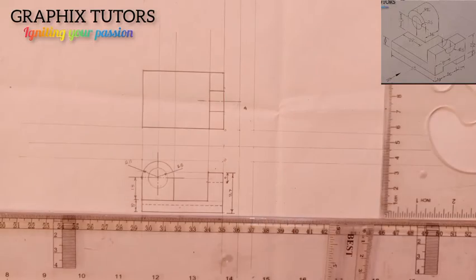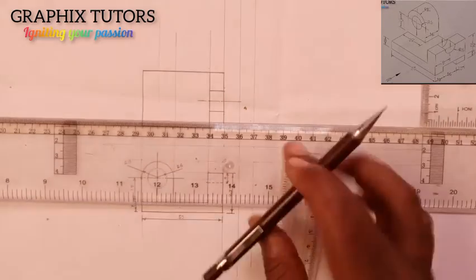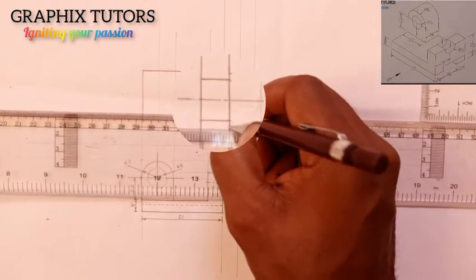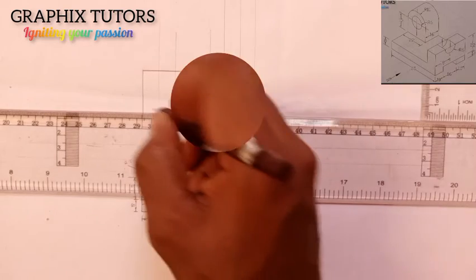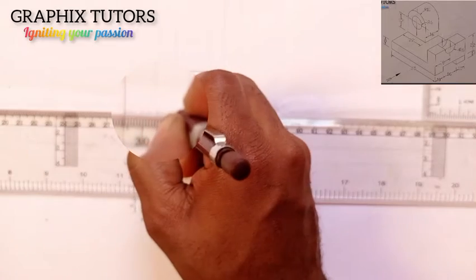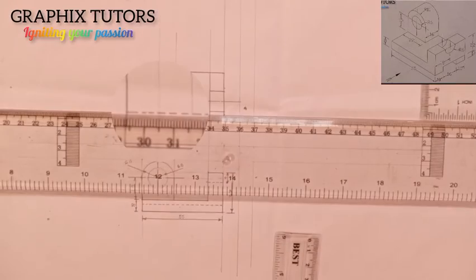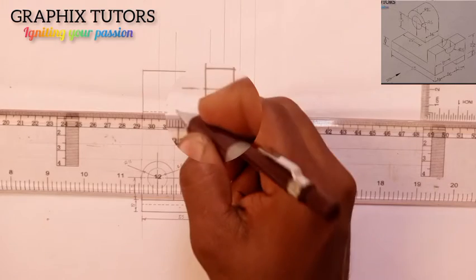Is that taken? So to show the hole that is going in, because there's a hole going in, I'll show it using a hidden line. So from this point, I'll draw my hidden line, a long one, short, and then everything should be the same.